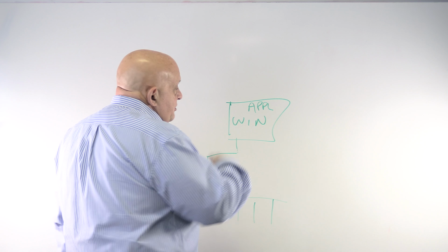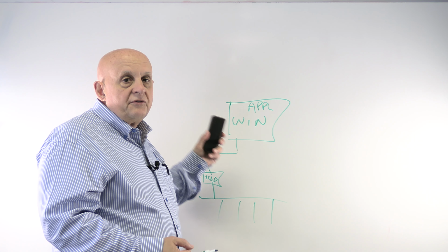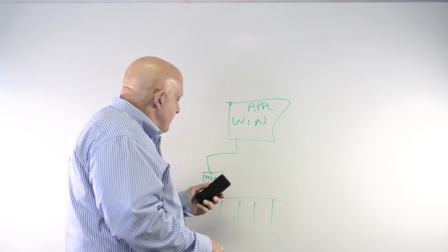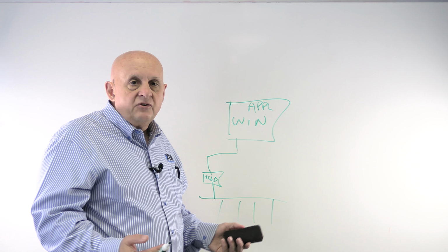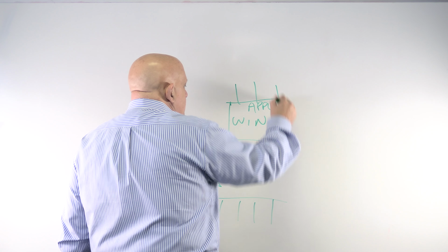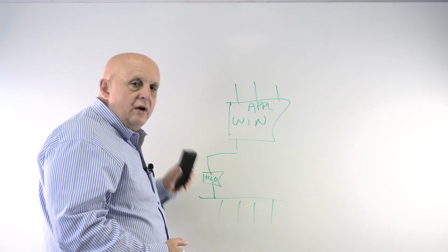So I'd say you're going to have an agreement with IT that there are certain Windows PCs that they're not going to update except at certain times when it's going to be advantageous to you. If you can get IT to agree with that, you take these Windows PCs out of the control system environment so that anybody who uses them is going to have to go through the ICS Defender, and then you're protected so that no matter what, they're only going to be able to do what you authorize them to do.